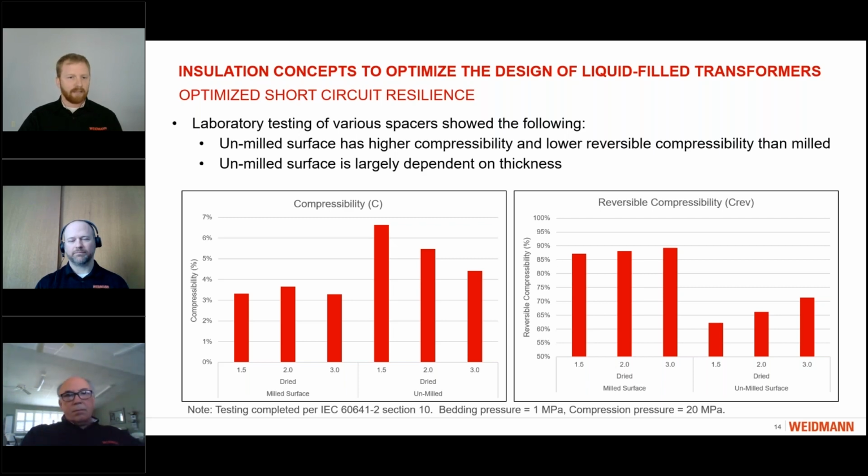However, when we look at the milled surface spacers, we have very consistent results that are really independent of the thickness of the material. So this compressibility is really measuring how much that material compresses under a known pressure.